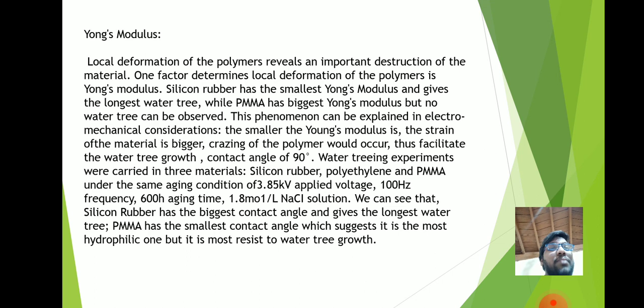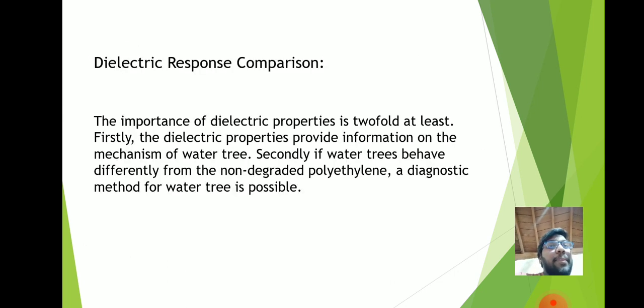Silicone rubber has the biggest contact angle, smaller Young's modulus, and gives the longest water tree. But PMMA has the smallest contact angle and a bigger Young's modulus, which does not give water tree growth. It resists water tree growth. Now let us discuss the last one, dielectric response comparison.